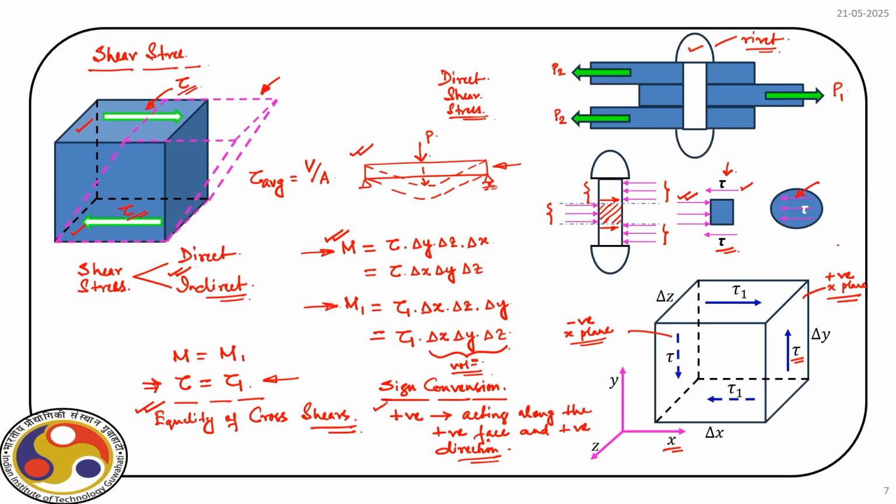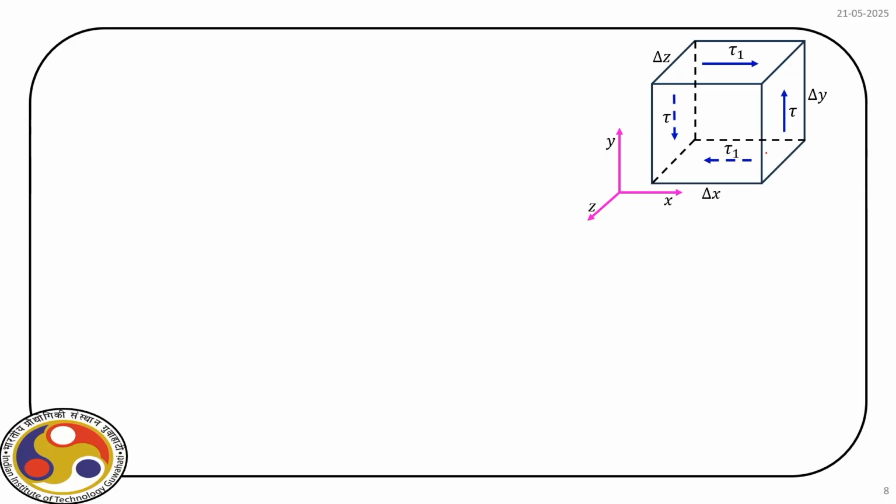When we go further, I will elaborate more on this, but keep this in mind that in case of shear stress, first we have to identify the plane, the positive plane and the negative plane, and on that plane we have to see along which direction the force is acting. That will give us the proper sign of the particular shear stress. Okay. Now, in case of shear stress, again as you can see here, we consider the same